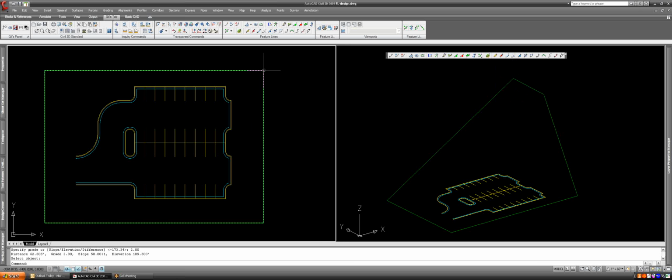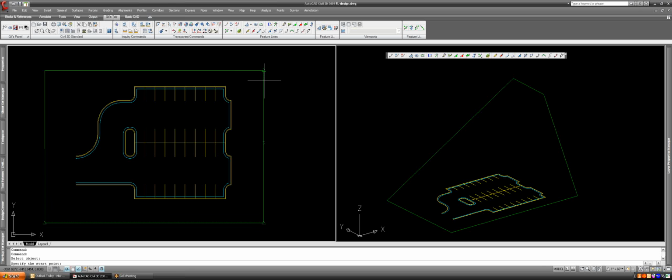We're going to do the same thing here. We're going to go from this point here up 2%. So we're going to use the exact same tool. Select our feature line, grab point A, press enter for correct elevation, grab point B, and give a 2% slope. Boom.